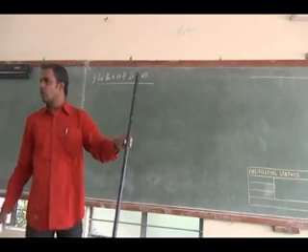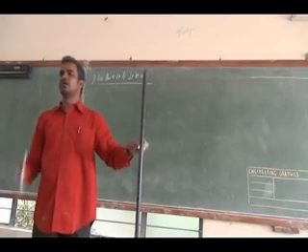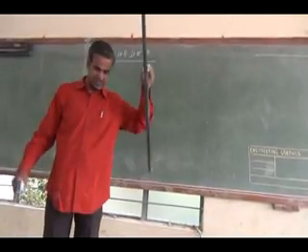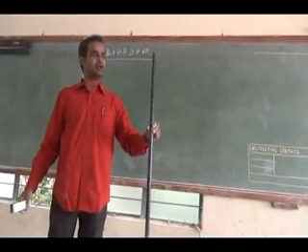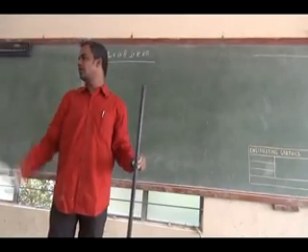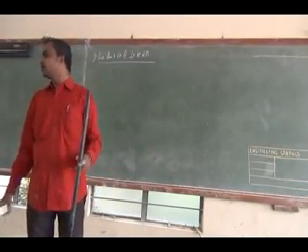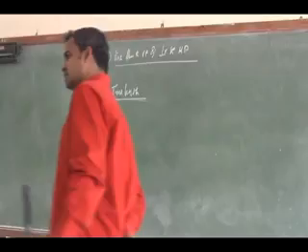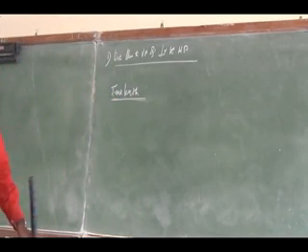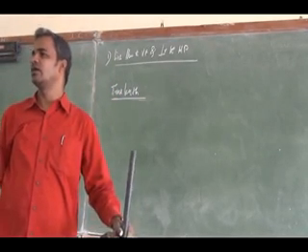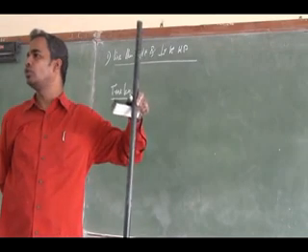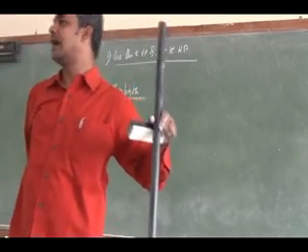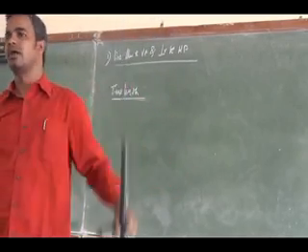So what will be the top view here? A point. Both the ends will be seen as a point. Since it is perpendicular, if a line is perpendicular to any plane, I will obtain a point as a projection in that plane. Clear? You make a note: the true length of a line is obtained in a view only if the line is parallel to the projection plane.